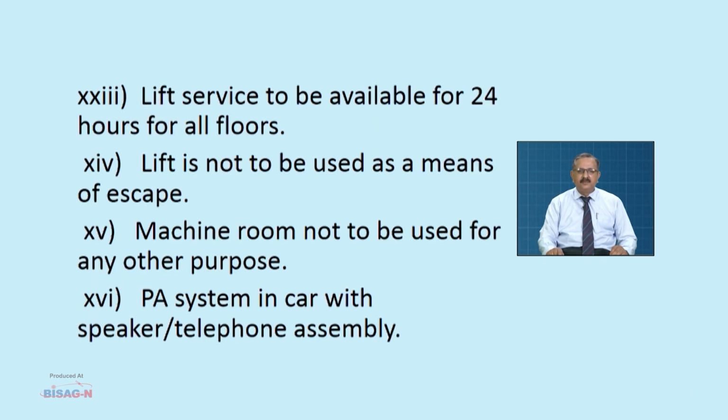Lift service to be available for 24 hours for all floors. Lift is not to be used as a means of escape. Machine room not to be used for any other purpose. PA system in car with speaker, telephone assembly.